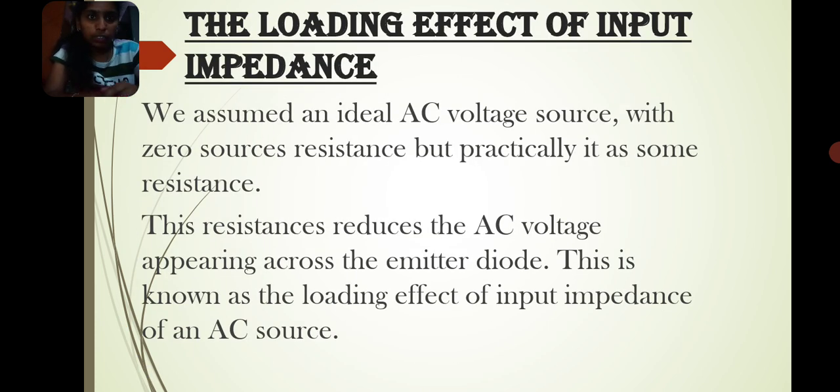The loading effect of input impedance. We assume an ideal AC voltage source with zero source resistance, but practically it has some resistance. This resistance reduces the AC voltage appearing across the emitter diode. This is known as the loading effect of input impedance of an AC source.